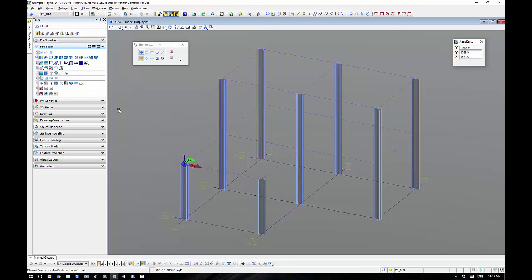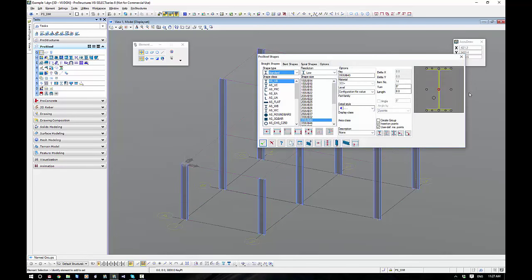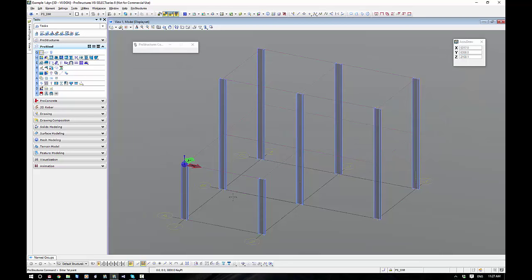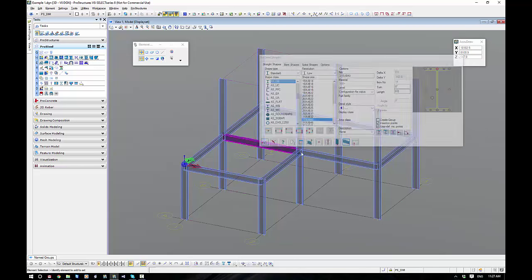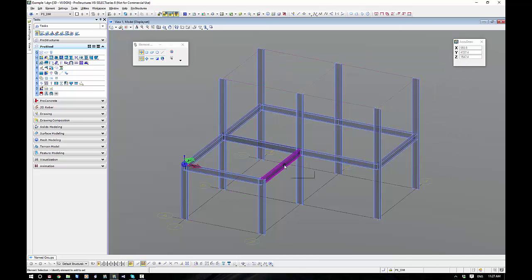Okay, it's still flat. I'm going to go back to my steel and say I want beams top of steel, and select the beam switch, and I'm going to draw a rectangle or a perimeter that the beams must fall within. How cool is that? It only works if you've got all the same size steel, otherwise you're going to have to run around and update it. Now, remember that handle I showed you before? Remember I said you can snap to other things. So if I snapped right up here or right down here, it's only going to drag in the direction it was created in.